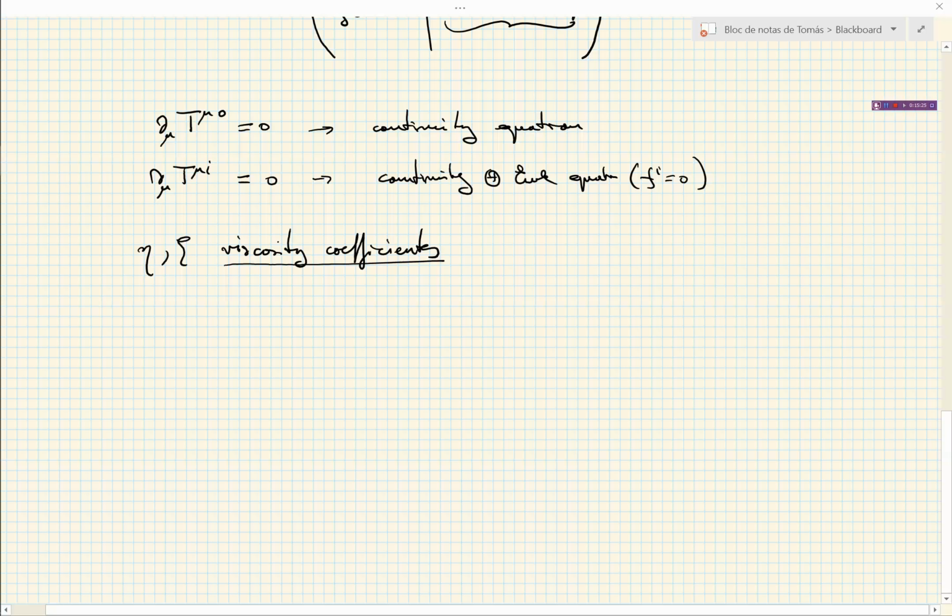Okay, so the Euler equation, taking into account these viscosity coefficients, takes this form: plus Vj. This left hand side is not modified, because it is just the total derivative of the velocity. And the right hand side, of course, this is still here because this is a source of densities of forces, but then there are additional effects which are internal. This is without considering external forces.